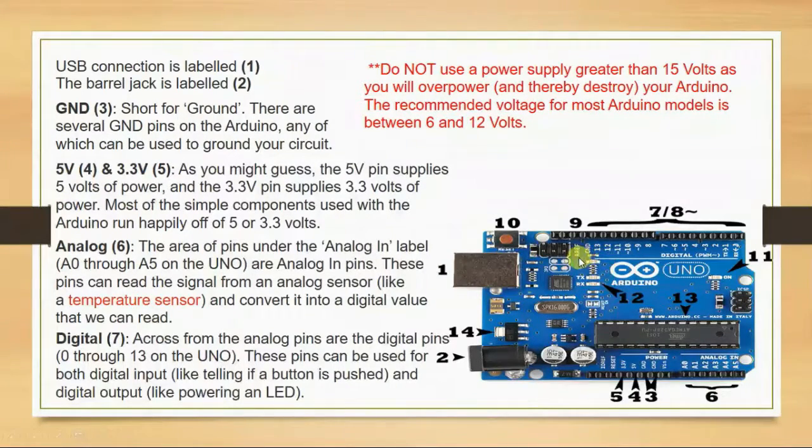Then on board LED is there, that is connected with pin number 13, and power LED is also there, which is over here. If your board is working, this LED should glow. If this LED is not glowing, something is wrong with your connecting cable or port. So you need to look out for that.